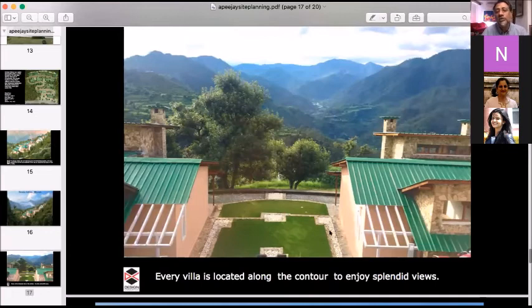So during the monsoons, they fill up. You can see the water gently flowing through that. And in peak summers, when there is no water, it still is an interesting element. Where my mouse is, you can see we created small lily ponds where the water collects. Then it overflows into this little pebbled square platform, which is connected underground to another platform. Then it goes to the lower one, and it collects in rainwater harvesting pits, which are at the lowest level.